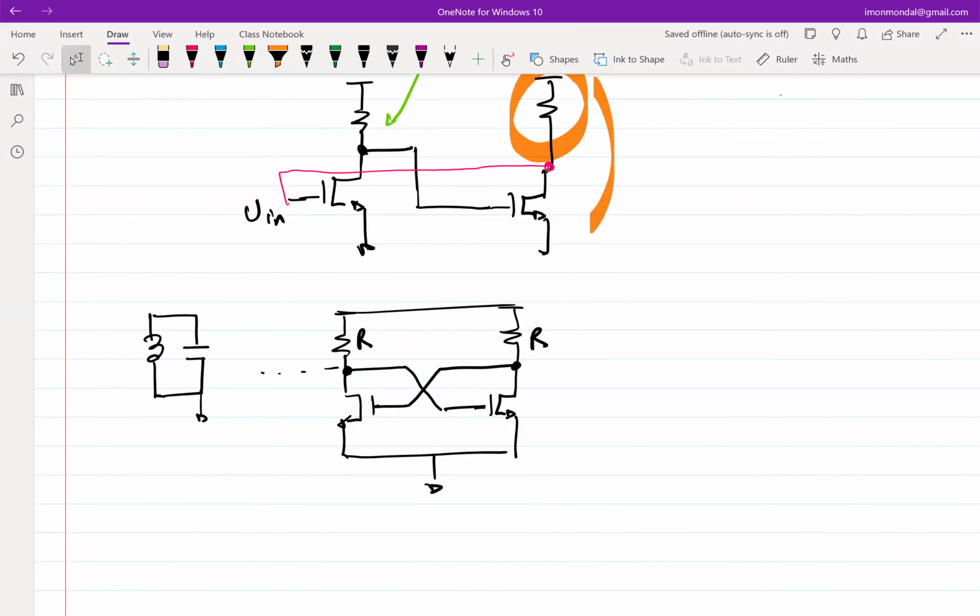Pardon? Tunnel diode, yeah, good point. So the point is that there are other devices which sometimes give you negative resistances. If you check the IV characteristics of some devices, you see they have a negative slope in some portion of their IV curve, which means that small signal wise they give negative impedance, and tunnel diode is one example of that.